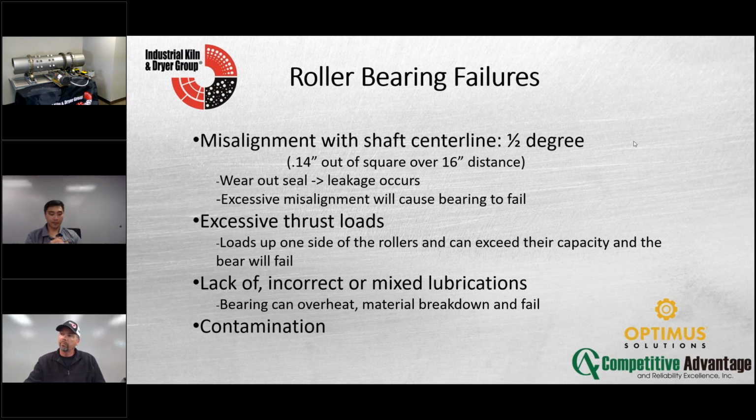Again, lubrication is all about the viscosity. High viscosity, think of it in terms of daily life, like honey versus water. Honey is, quote, thicker. Water is thinner. If it's thicker, it creates a thicker film, and that film will protect the metal contact.